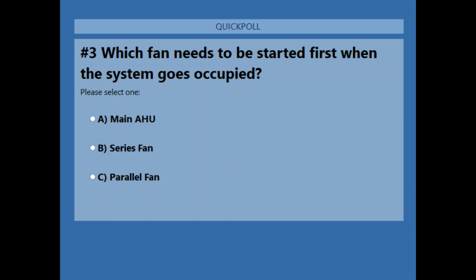When the building goes occupied, when you're doing the air balancing, those filters come off the inlet plenum, and you do not put new filters back on there. There's not supposed to be a filter on the inlet side of a fan power box in a normal operating system. Now, if you have some filthy, dirty building or whatever, okay, maybe you want to do it. But then again, if you have a filthy, dirty plenum cavity, I'm going to ask, why are you sucking that air in and putting it into the zone to begin with?